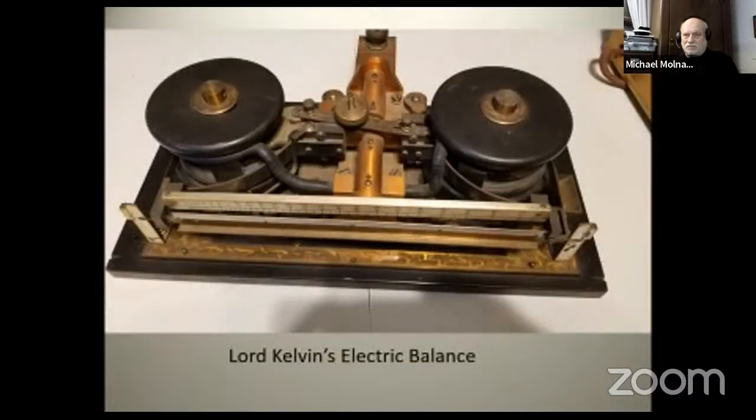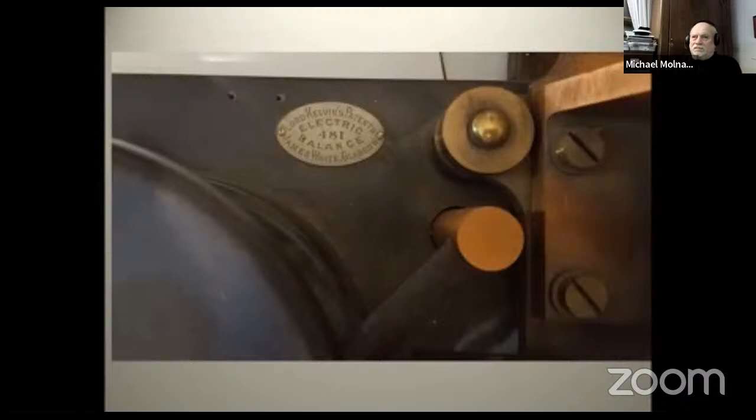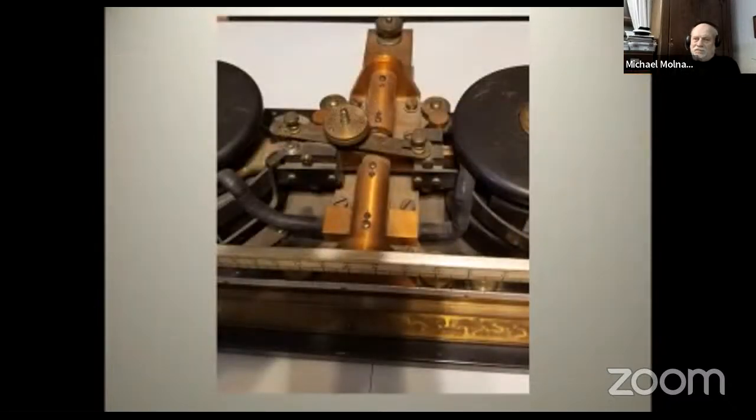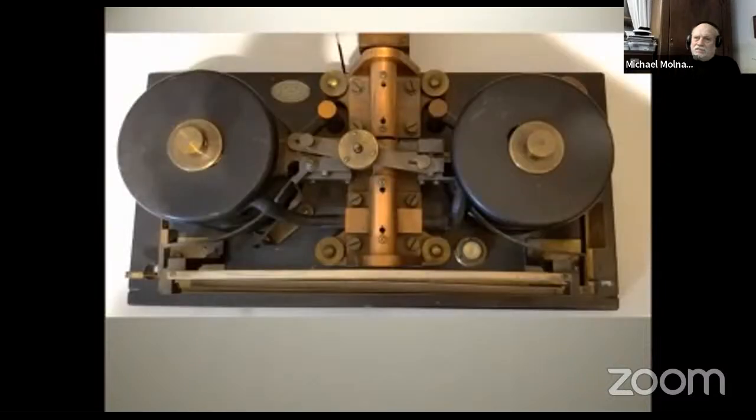This device doesn't look like an electric meter at all. A tabletop unit, it weighs in at 60 pounds. It is a Lord Kelvin electric balance built by James White in Glasgow and measures electrical current, also dated from the 1890s. Current is applied through the copper connections at the rear of the meter. The coils and discs are actually on opposite sides of a balanced beam. The heavy coils are wound such that on applying a current, the magnetic field pushes one disc up and pulls